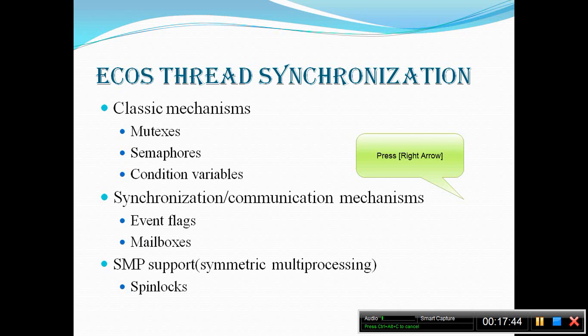For example, bit 0 could represent completion of a specific I/O operation, making data available, and bit 1 could indicate that the user has pressed a start button. A producer thread or DSR could set these two bits, and a consumer thread waiting on these two events will be woken up.